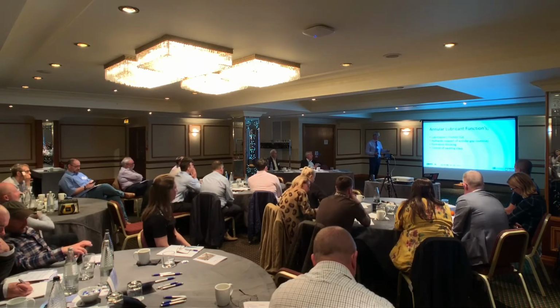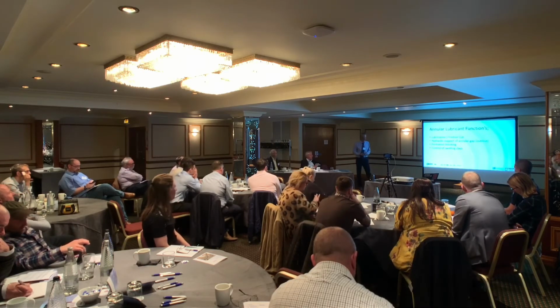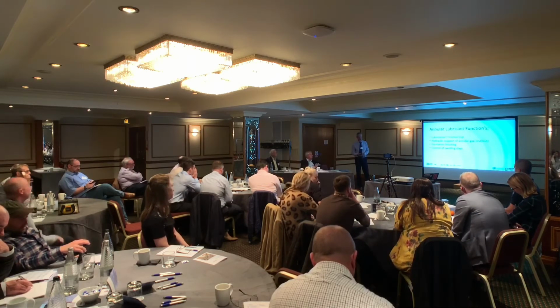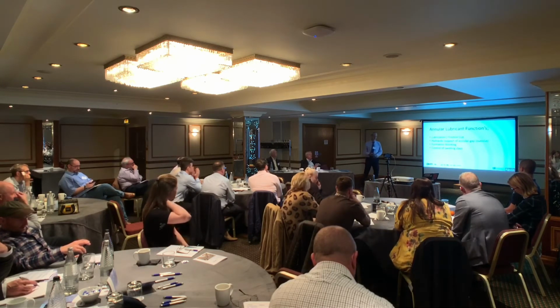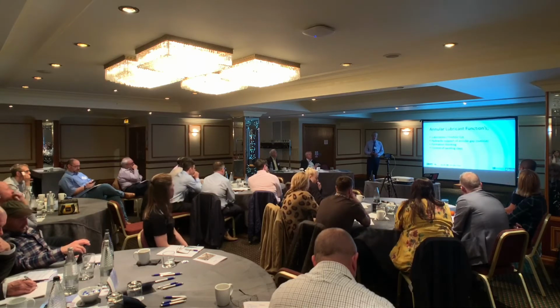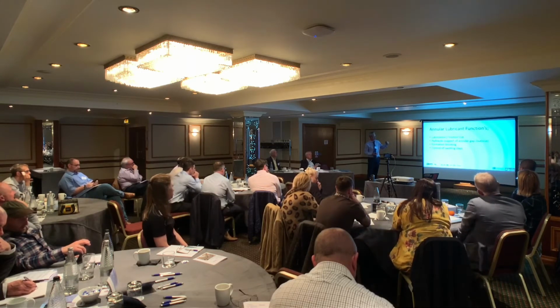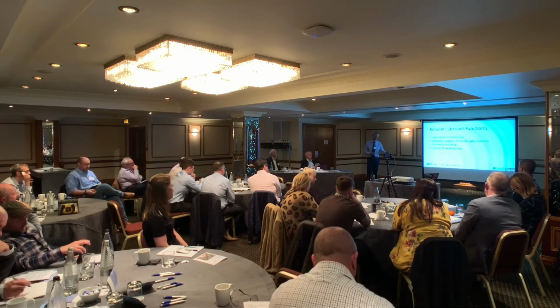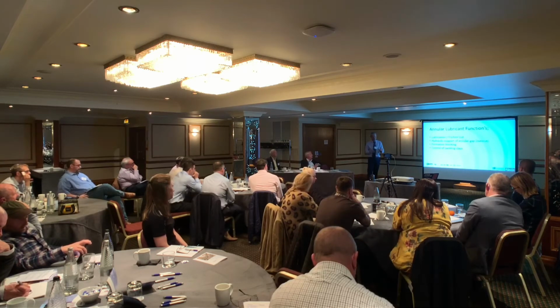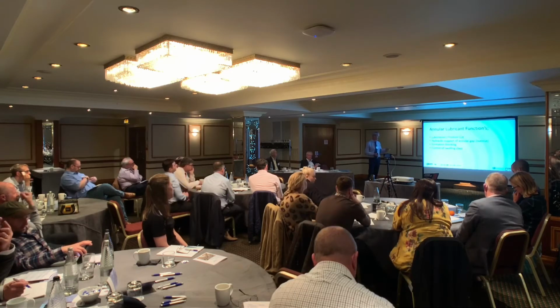And also the control of swelling clays. So as an example, London clay and most clays have a percentage of their content made up of materials like bentonite and other materials called smectite, which is common in London clay. And there are capping polymers that you can insert into your lubrication, which will cut off water getting to the clay, which reduces its swelling capacity.